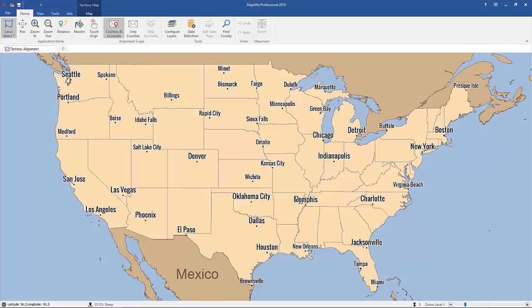So now that you've loaded your geography here based on counties, also known as FIP codes, you can start importing your data. But before we begin that, it's important to understand what a FIP code is, because if you just import county names, that won't work in the software because there's a ton of different Orange counties, Fairfield counties, what have you. So you have to use a unique identifier called a FIP code, and that's typically a 5-digit code. For more information about FIP codes, you can look it up on Wikipedia.